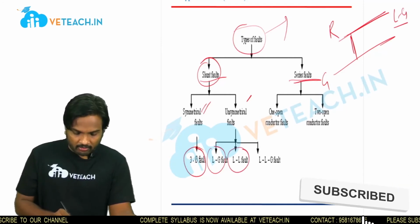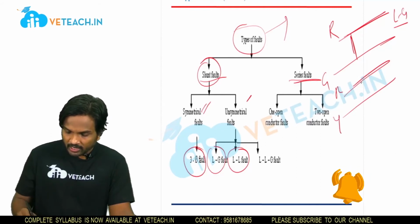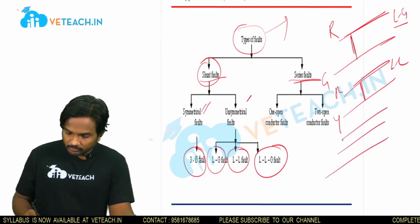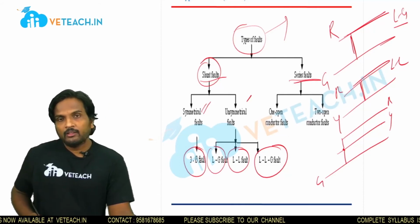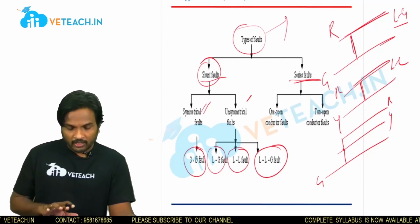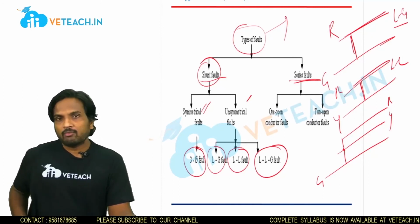A line to line fault means a fault occurs between two lines, R and Y. If a fault occurs between two lines and ground, that is R, Y and ground, it is called a double line to ground fault. Line to ground, line to line and double line to ground faults are called unsymmetrical faults, whereas a three-phase fault is called a symmetrical fault.